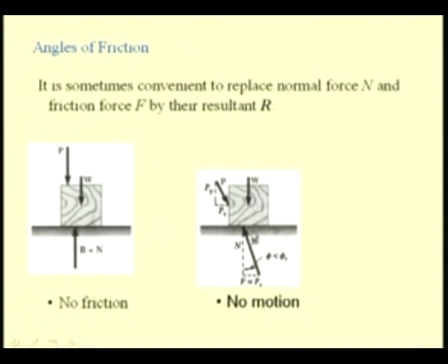and for this condition a frictional force F develops which is equal to this Px in magnitude and opposite in direction of this load Px. So, the resultant of this frictional force and the normal reaction is R, and now this R is inclined to this N. The angle of the same, phi, is given by this relation where tan phi is equal to this F by N.